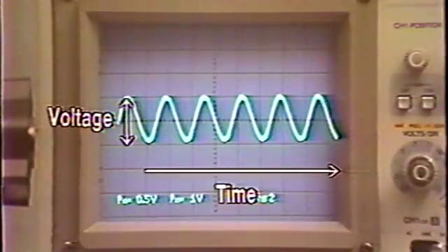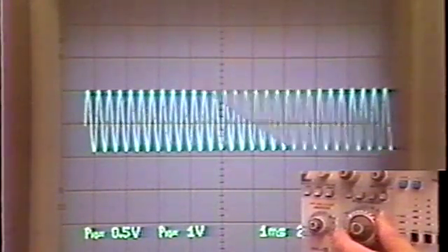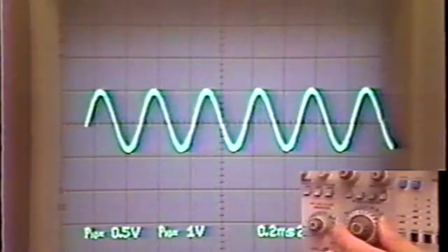The horizontal axis on the screen of the oscilloscope indicates time, while the vertical axis indicates voltage. Both must be adjusted in accordance with the waveform being observed. The horizontal axis, or time, can be expanded or compressed using the sweep time dial. One grid on the screen is used to display the time to which the dial is set.